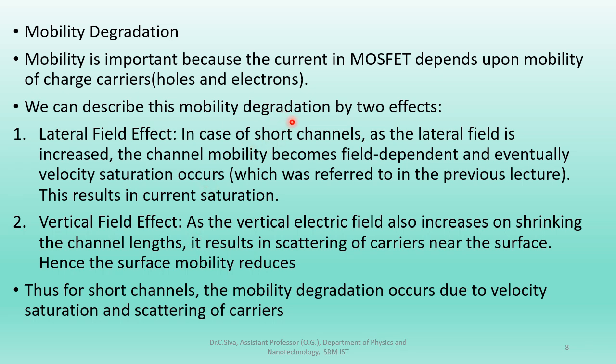Strong lateral fields cause velocity saturation. When the lateral field is increased, the channel mobility becomes field dependent and eventually velocity saturation occurs, resulting in current saturation. So mobility has been reduced.